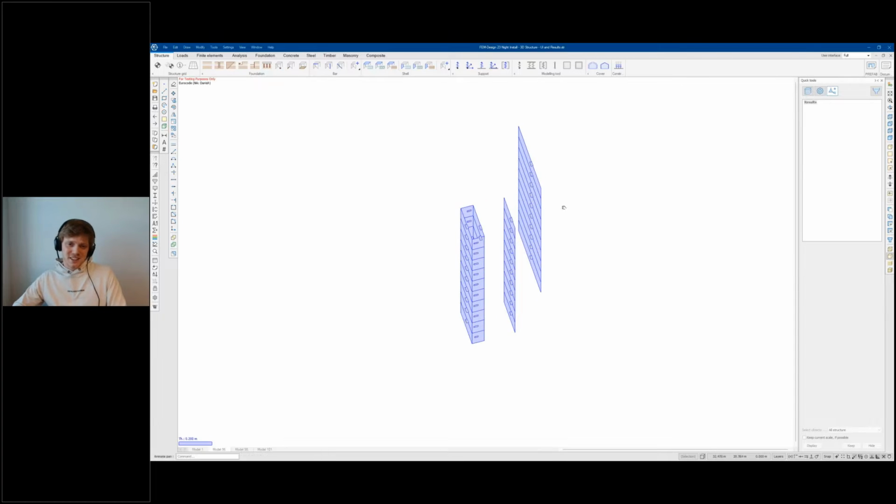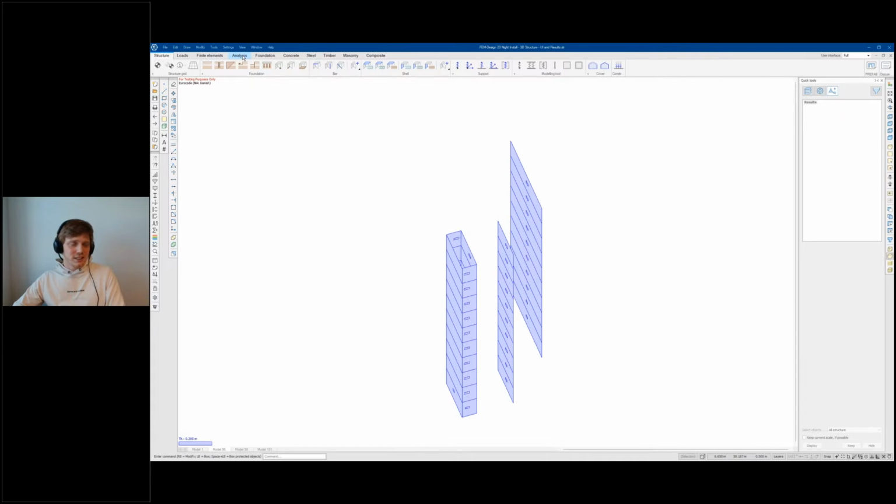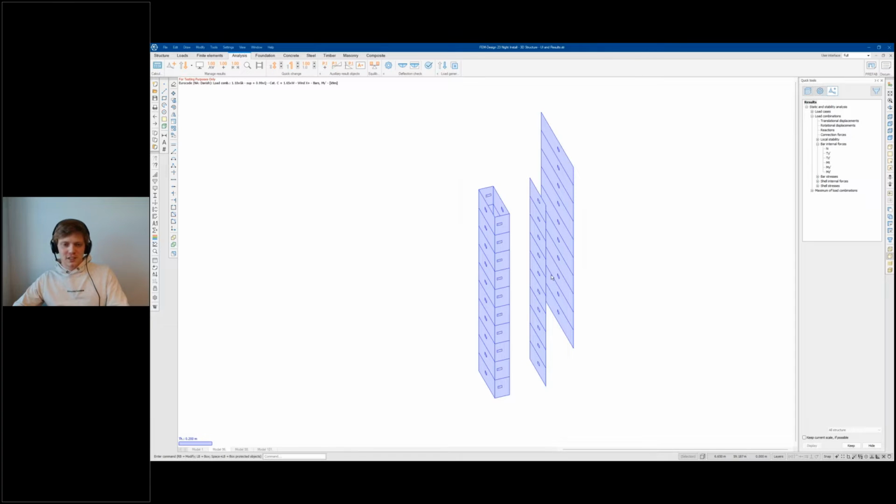Now you'll see it works for anything. It doesn't have to be a core, which is basically a bonus. But let's say I wanted to see, in this case, just all my walls in the structure. If I could get all these results inside these and get it displayed as simple internal forces, like a normal force diagram, moment diagram, and shear diagram, as if it was a virtual bar, I can now do it. So this is the virtual bar tool. And then you just basically draw your bar.